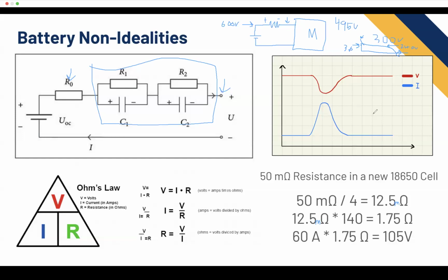The other way to help solve this issue is just reducing the resistance in the pack. If you take the bus bars and you just sand them all and make sure they're shiny and clean before you assemble it, you can actually reduce the resistance by quite a lot. We assembled our first segment and it had quite a lot of resistance. And then we just sanded them down and reassembled it. And it's like, oh wow, it's like 2 ohms lower, which is a lot here, right? But yeah, reducing resistance at every single spot is critical.